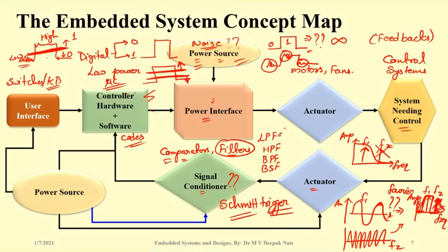One threshold value is very risky most of the time, because sometimes a small spike like this can even trigger the higher value. But in this case, no, it will not switch, or it will only switch when the signal actually crosses the higher threshold value also. So remember this: the signal conditioner is very important, and of course then there will be a feedback which again goes to the microcontroller to further provide more robust interfacing with the signals.